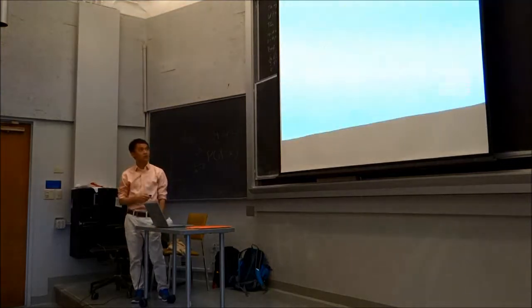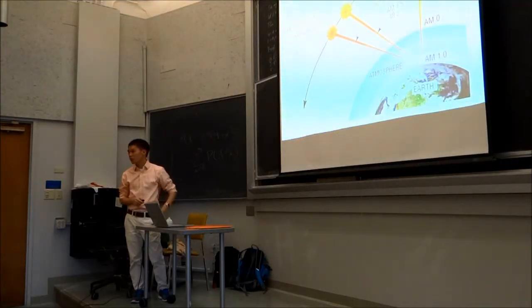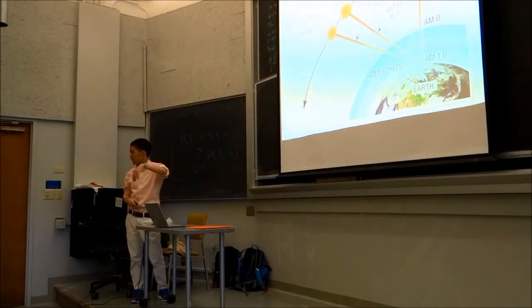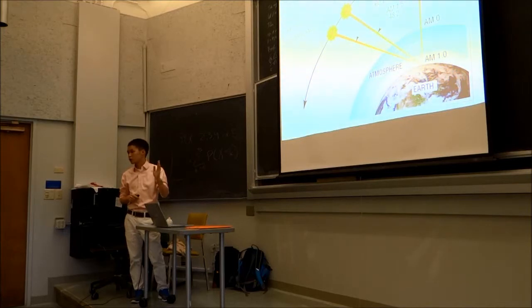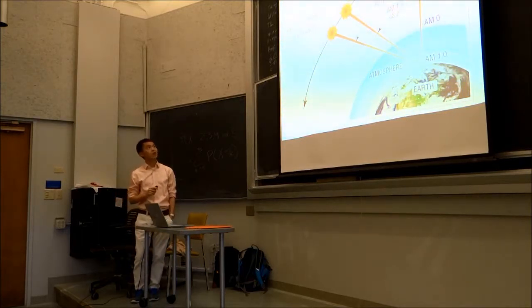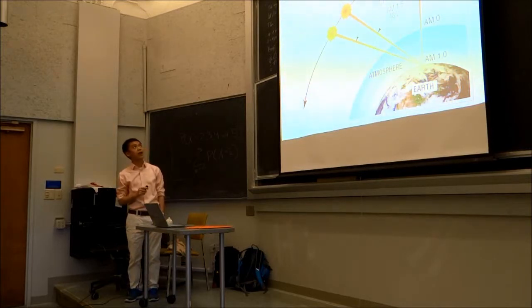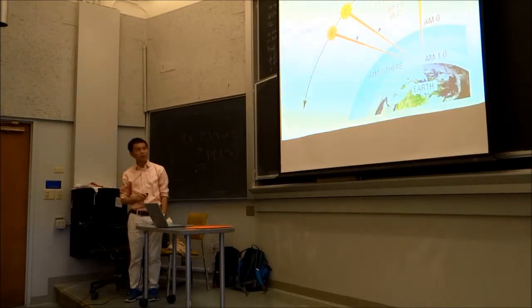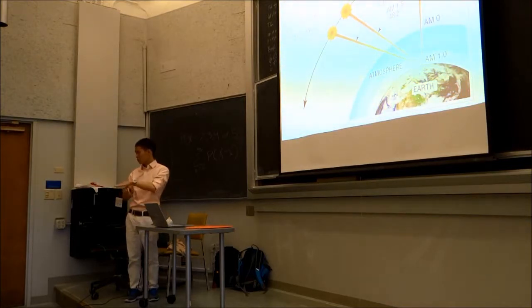This figure shows you that in the summer, in some places in the United States, you can almost have a perpendicular angle of incidence during noon, but in winter you cannot. So you need different angles to optimize for them. What I want you to understand from this picture is that there is something called angle of incidence. Basically, the angle at which light comes in onto your solar panels.